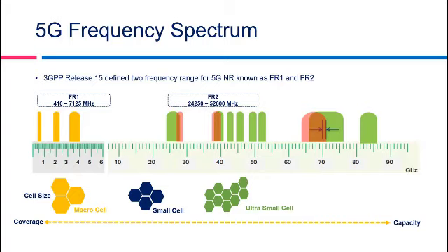So as we go higher in the frequencies, we can get a larger capacity, and if we go on the lower bands, the bandwidth will be less, so those bands can basically be utilized for the coverage requirements.